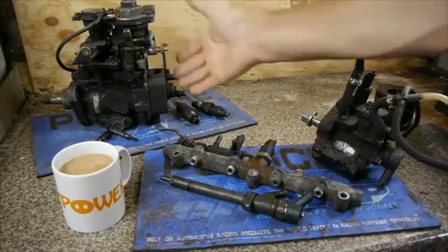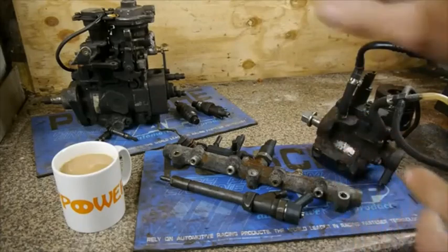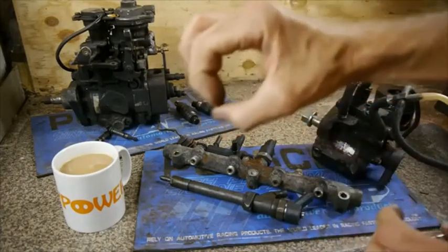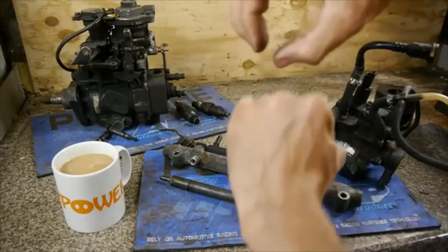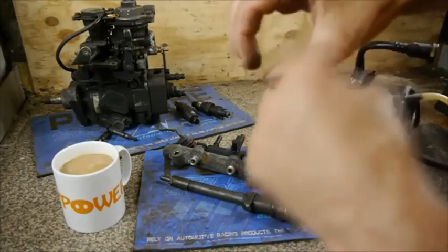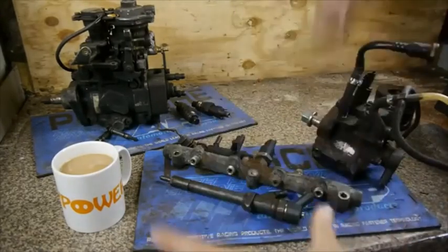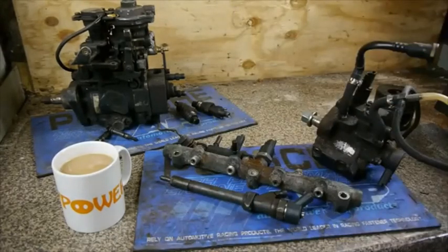As opposed to the XUDs, the old designs, the old heads, the indirect injection, well, they had a little port, a little bit like that bowl, inside the head with a little gap. So as the piston came up to the head, all the air swirled inside, it injected into the sort of swirling chamber, the swirl pot, and then came back out and exploded, bang, pop, wallop, and your piston went out the side of the engine.